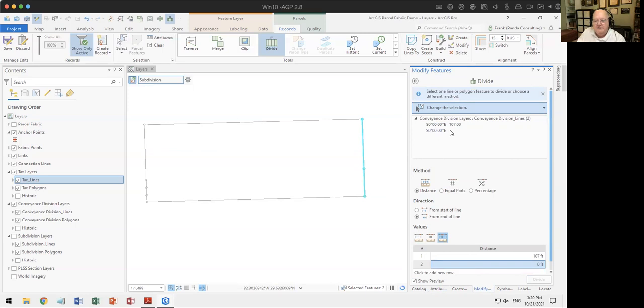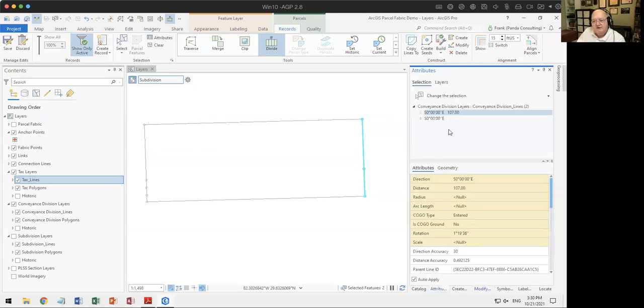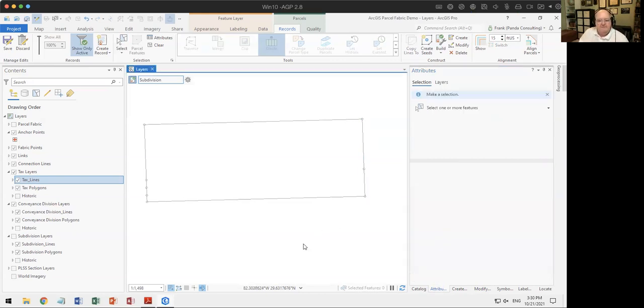on here, note, let's go over here. On the one that I actually entered, it says 107. On the one that I did not enter, it did not calculate the value, and it did not say whether or not it was entered, because it did not retain any COGO attribution on there, even though there was attribution initially. So if you want to maintain this, make sure that you populate it all the way and just tell it to distribute it and handle it that way. All right.